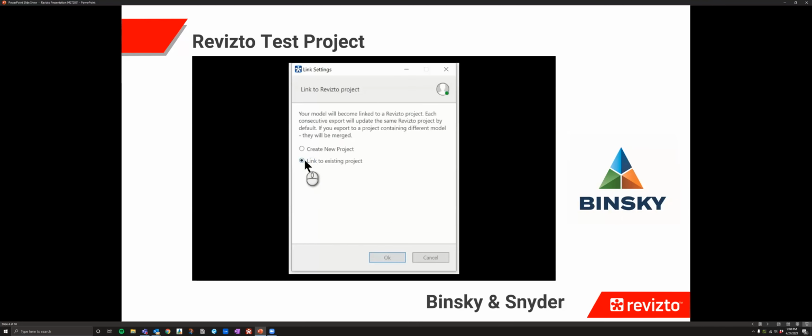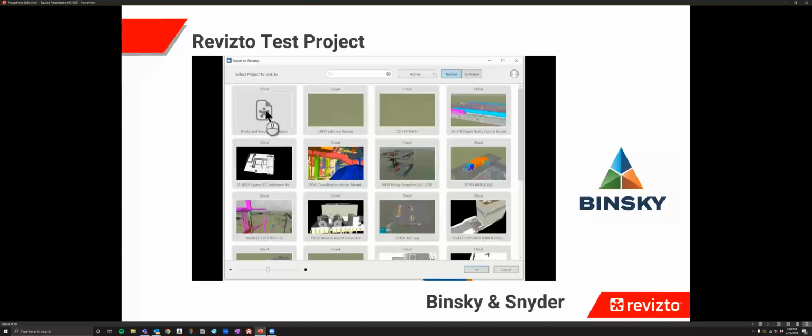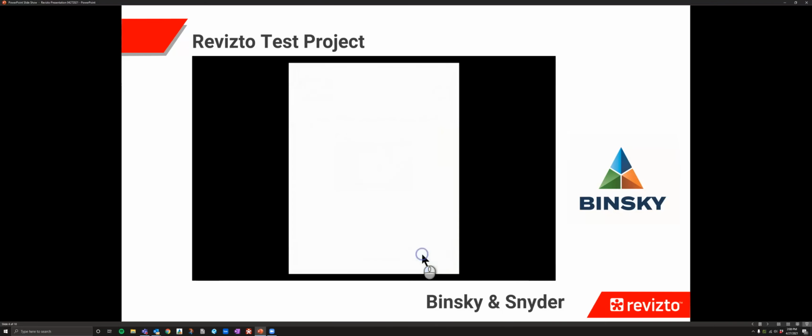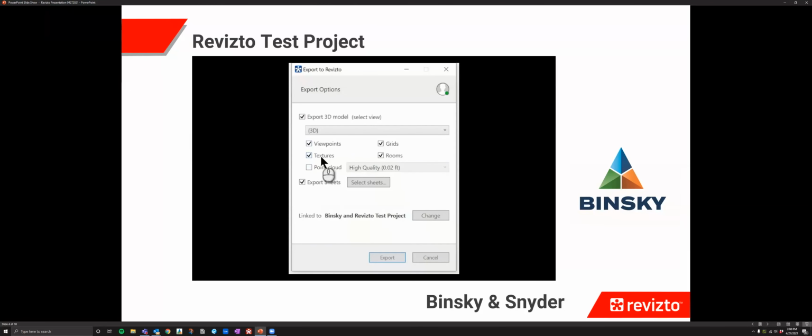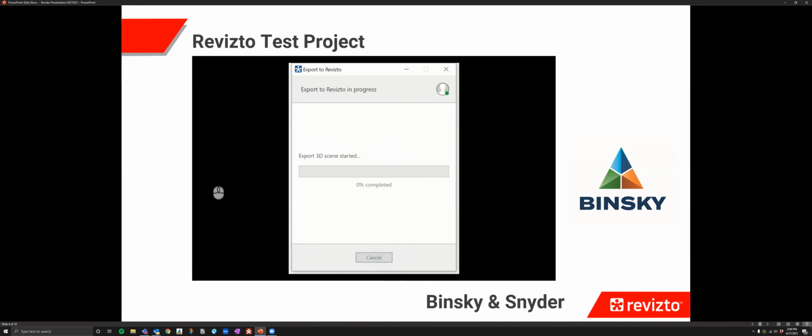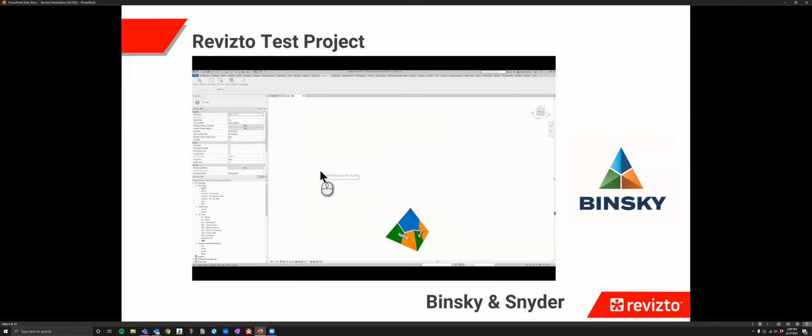And then when I do the push, you're not going to see the NWC, the Navis part of it. But here you're going to append as a new model also. But whenever we're updating it or you manually update it, you always want to update that existing model. So if you were pushing a model and you're adding extra steel to it that you just got an NWC for, just add it in there, save, and you're always going to append to the existing model. But here, since we're doing the new project, we're just pushing out new stuff. There you go.